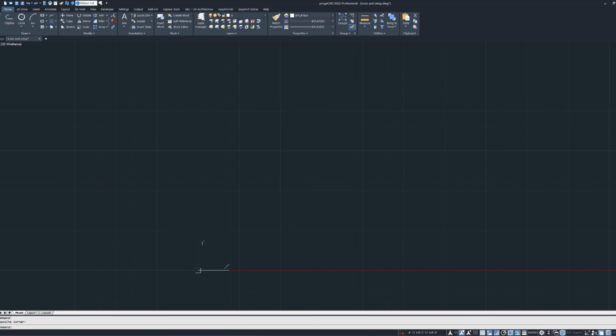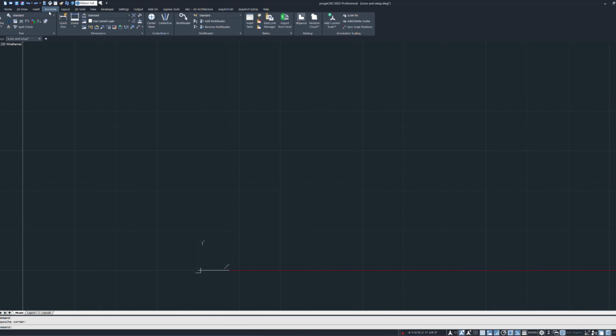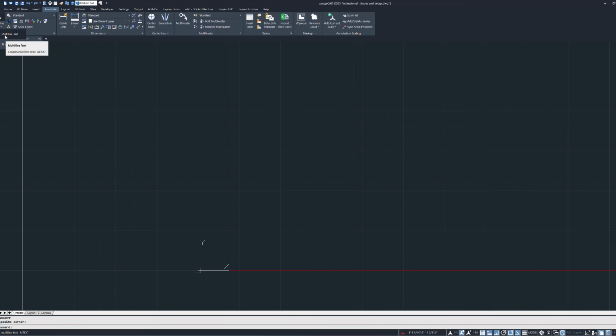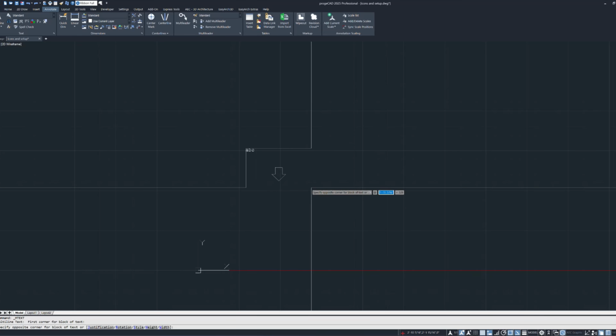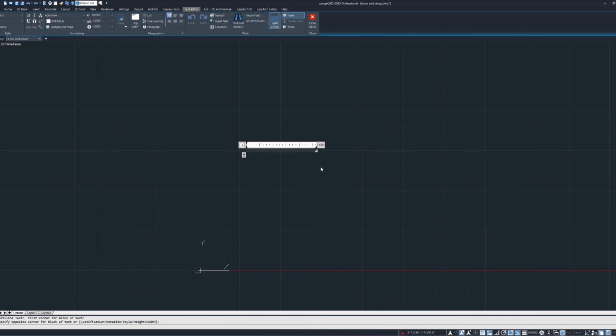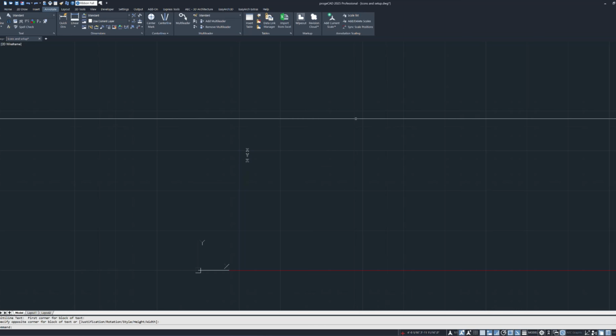Now we will demonstrate how to create the cube shown in the previous examples. First, find a good font that will be good enough to show as an extrusion within the cube. A fatter font will be better since it will be easier to see from a distance. Since this text will be just one letter, we choose to use an mtext text object. Enter X on the first line, Y on the second line, and Z on the third line.